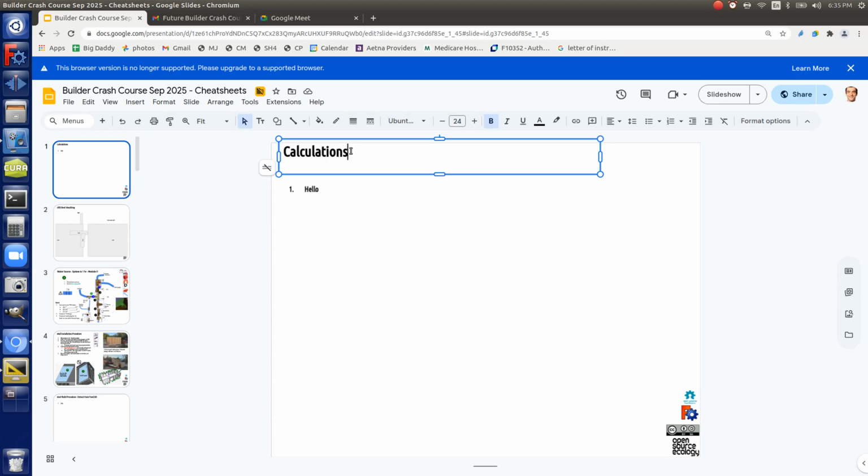Now you might see a bridge that's made of a triangulation of that, because that's what prevents it from buckling in the other directions or torquing or doing other things. Well, I'm trying to get you to understand the very basic things, like what we're working with here. Now, what if that thing was made of compressed block? Let's just play with these numbers here. The walls next to it are 6-inch compressed block. How much can they hold on the top?